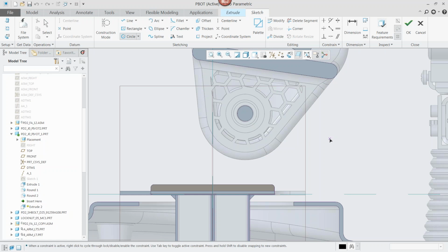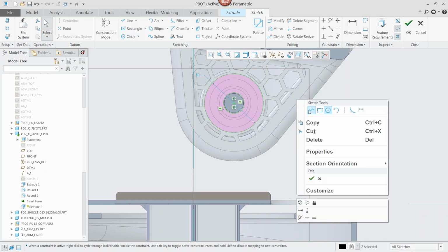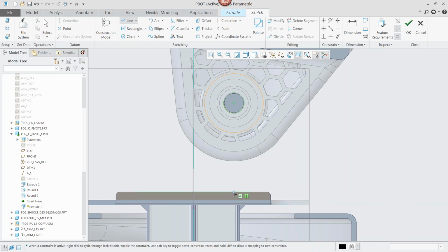With Creo 4, we have the ability to add in references on the fly. Anytime I highlight over some existing geometry, whether that's a sketch line or, in this case, part of my assembly, I snap straight to it and get references such as the endpoints of those lines and the center points. So if I highlight over the circle, without having to create an external reference beforehand, I can just start to build out two circles very quickly, then right click into another sketching tool. We're really just trying to improve how fast we can build out these sketches. We're building lines and circles all the time, so let's just do that a lot quicker.